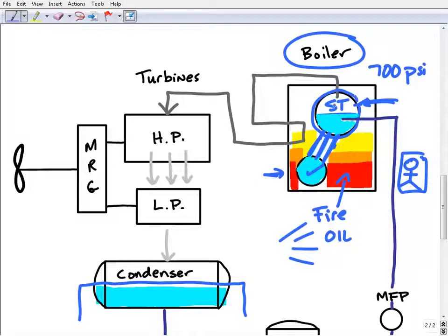But this particular steam is not the steam that we're going to use in our engine yet, because it's saturated steam. In other words, if you microwave some water and put your hand over it, you feel steam coming up, but you also have that condensation, the wetness to it. So what we want to do is get all the water out of the steam, at least the best we can. And I'll tell you the reason why in a second.